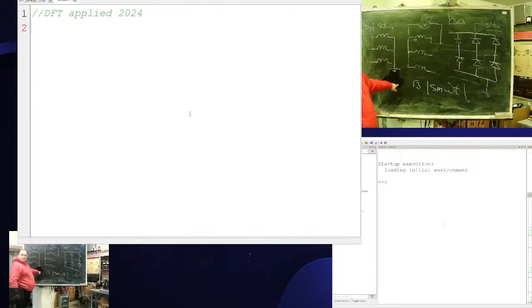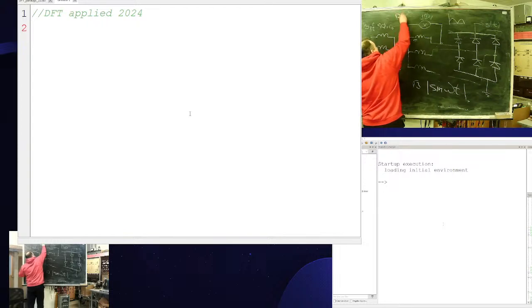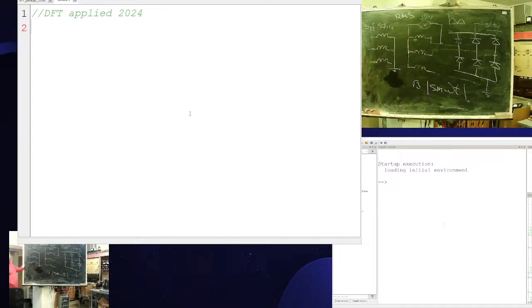One moment, I left space. For what did I leave space? 10 volts is an effective value or amplitude. Effective. My voltmeter pretends to be an RMS, so these 10 volts are RMS. But I need a magnitude description. For a pure sine, the factor between RMS and magnitude is the square root of 2. That means I need the square root of 2 times 10.